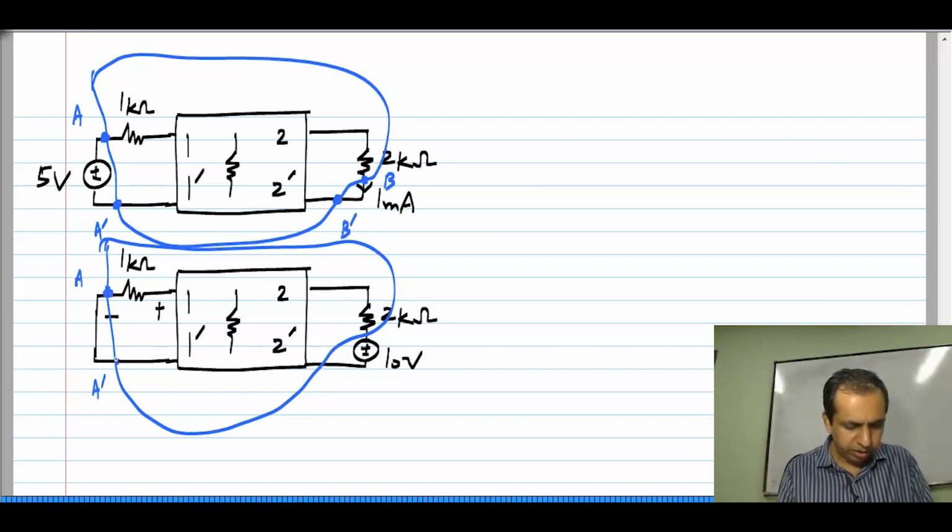I have to take the same thing that I took earlier, where originally we had a short circuit, we have now a voltage source, and this makes sense. Basically, we get this by reducing this voltage source to 0. You are not allowed to change the network, but you can change the values of the independent sources, in all these problems. When you set a voltage source to 0, it becomes a short circuit.